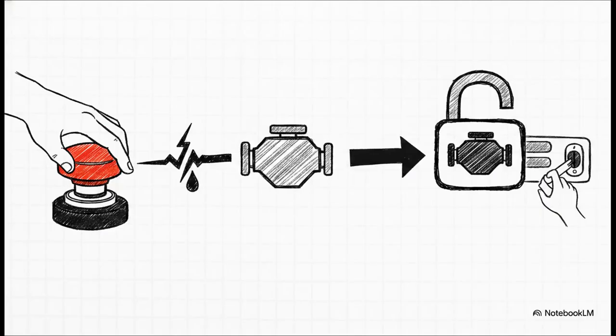Finally, we have to talk about the ultimate external control, the emergency stop, or e-stop. Now, unlike our manual overrides that force the engine to keep running, an e-stop is designed to kill it instantly. These are hardwired inputs. The second one gets hit, the ECM instantly kills fuel injection via the basic engine logic. But here's the crucial takeaway. An active e-stop causes a latched shutdown. You can't just pop the button back out and hit start. Nope, it demands a hard reset. You have to completely cycle the key switch, power to the ECM, to clear that latch before the engine will ever crank again.